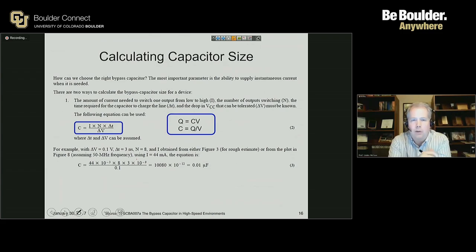But the application note also talks about larger capacitors called bulk capacitors. Has anybody read the application note yet and can talk about what this is? Okay, so a bulk decoupling capacitor is basically a larger reservoir of charge. It has a larger capacitance value. It may not be as fast to respond to changes in the load circuit, but it's faster to respond than the original wall adapter or power source that you're using for your embedded system.